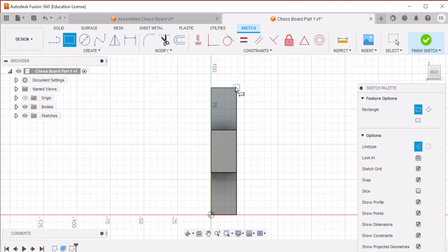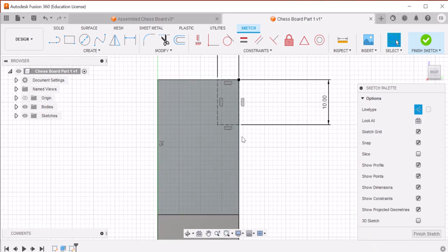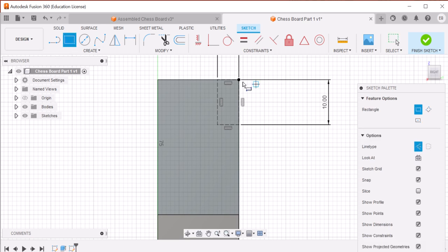So I'm going to go from the top corner and click and drag out, and I'm just going to place in a 3 at the top. Actually, no, let's change that to 5. A 5 at the top, but 10 millimeters down. Now I have placed that construction line in there so that I know that when I select my 2-point rectangle, I want to come down 10 mil from the top to place our first rebate in.